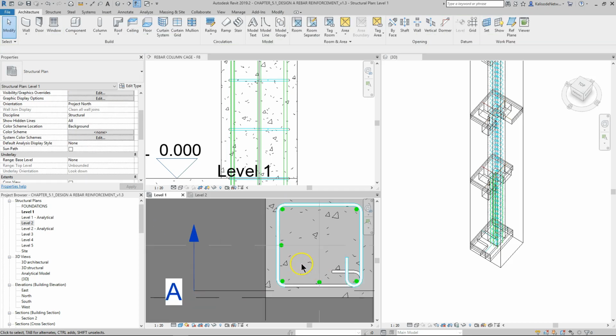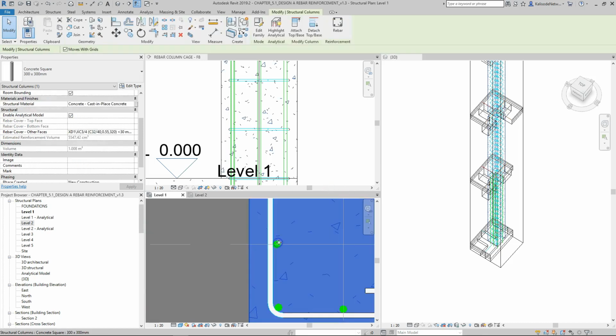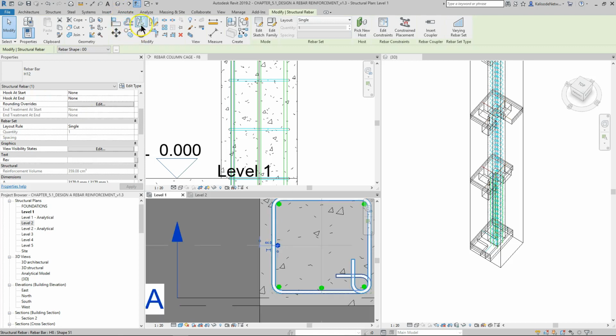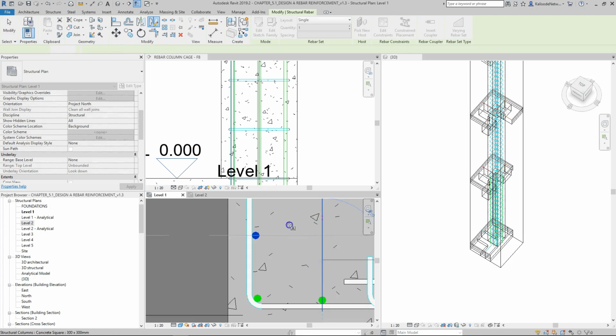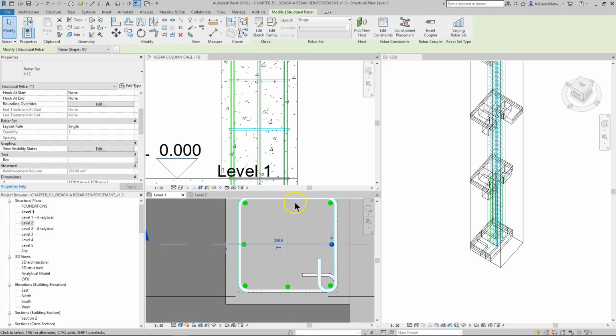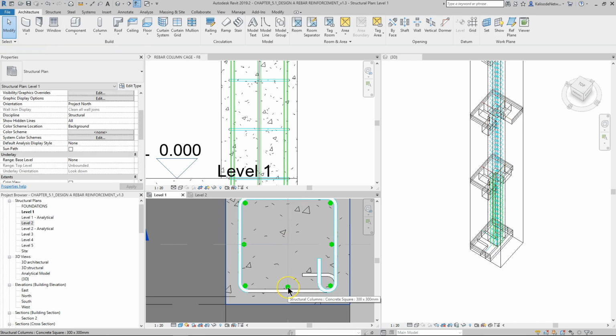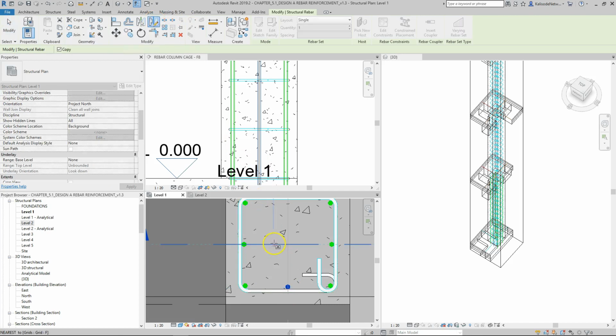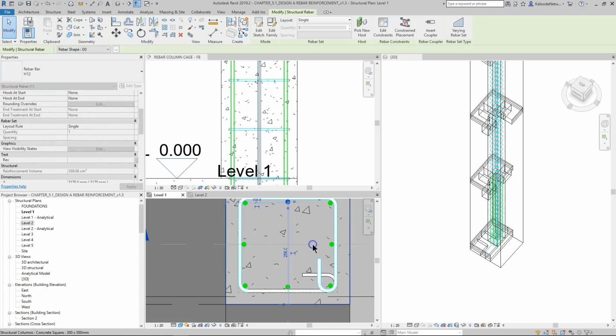And I would say that now we use a different trick. So I select my rebar and I go on to mirror draw axis, and here is appearing one, and I select this one. It is not seeing the pointer, the rebar. I press tab, now it is selectable. I select it and I do again draw axis, shortcut the M. Perfect, we are good to go.